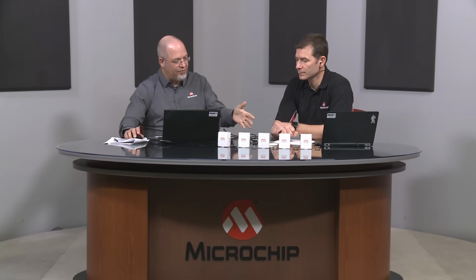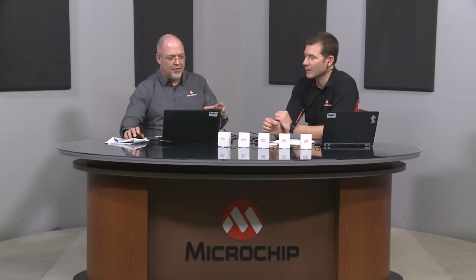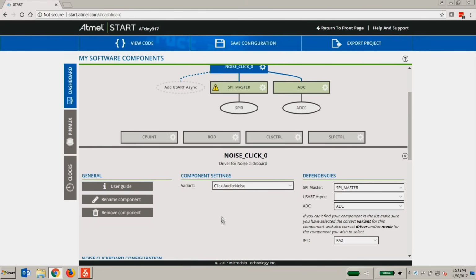And Jacob, that's a feature on the eDBG, the MEDBG, the serial monitor, correct? Yes. So what you have there, I already mentioned the power monitoring, but as you say, we also have a serial bridge that can take it from any serial interface and stream that to the PC. So it's a bridge between, in this case, UART and USB, and you would then connect to a terminal.